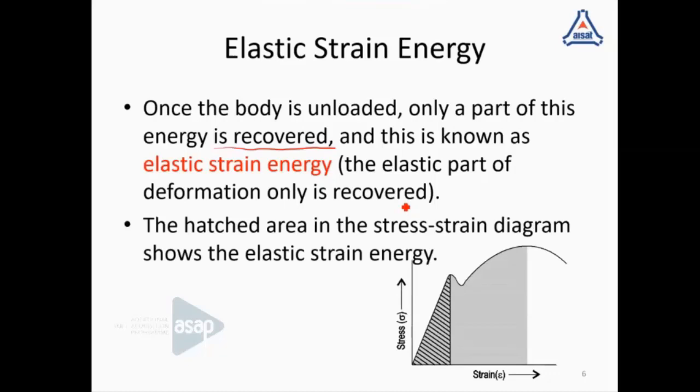And in this elastic region, we can have different materials behaving in different ways. In cases like steel, the deformation can be assumed to be linear. The deformation and load, or stress and strain, are proportional, and we can have a linear curve for the stress strain curve diagram or load deformation curve.